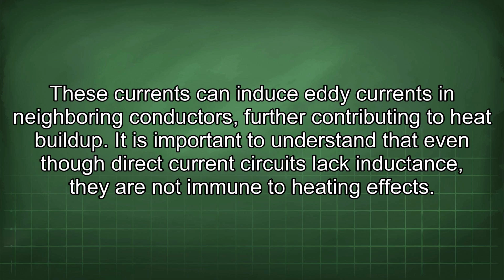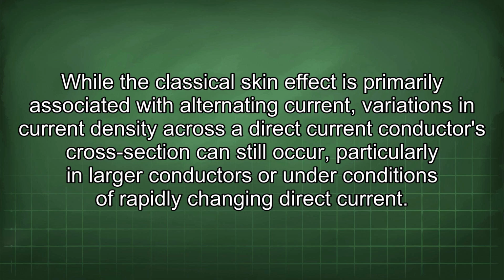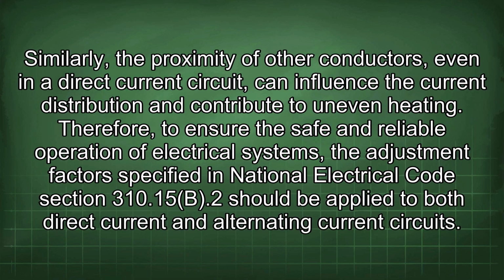It is important to understand that even though direct current circuits lack inductance, they are not immune to heating effects. While the classical skin effect is primarily associated with alternating current, variations in current density across a direct current conductor's cross-section can still occur, particularly in larger conductors or under conditions of rapidly changing direct current. Similarly, the proximity of other conductors, even in a direct current circuit, can influence the current distribution and contribute to uneven heating.